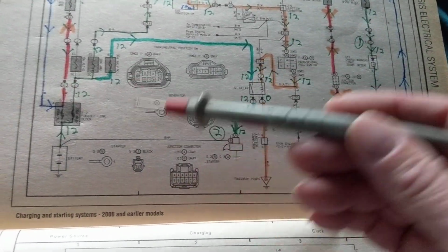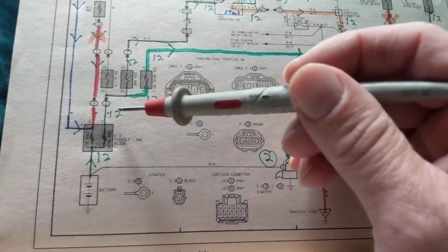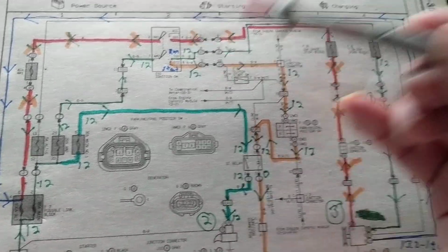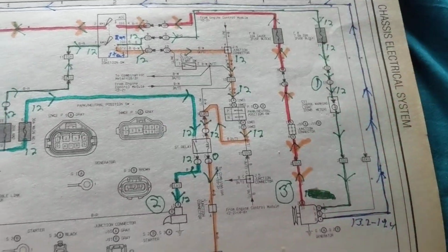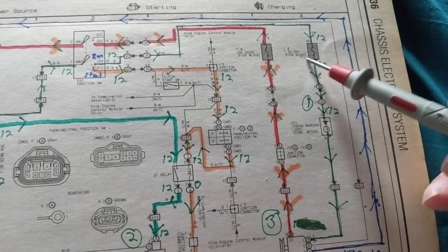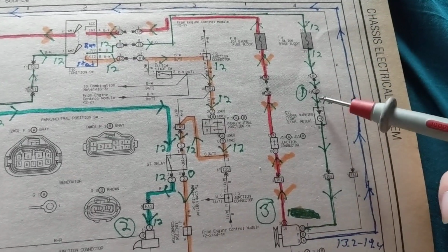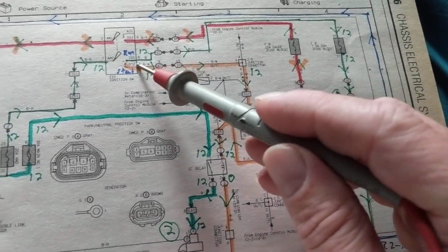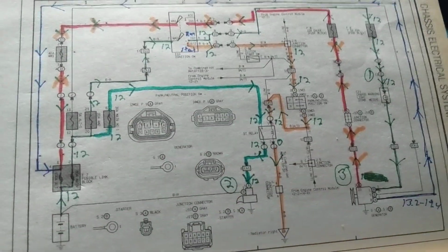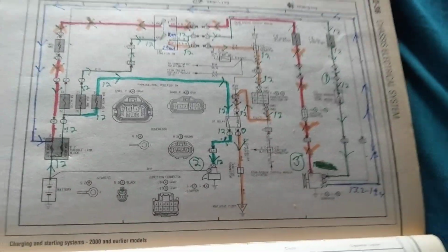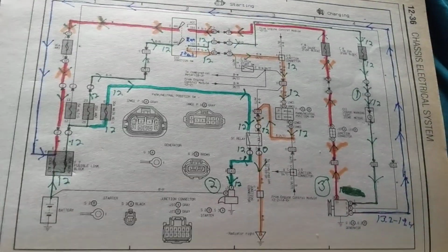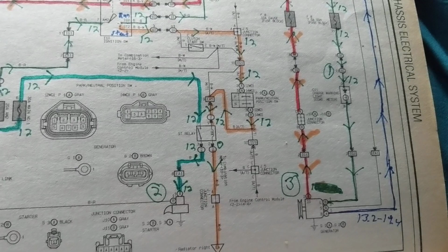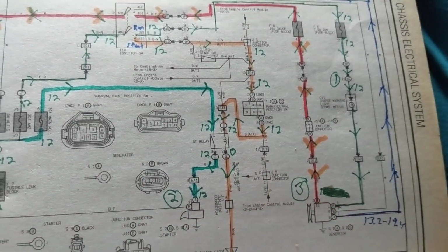This is a pro from a meter. Without even putting a meter at this point, or this point, or this point, you saw yourself when this lit, automatically the ignition switch must be good, the fuses must be good, without even putting a multimeter on it. This is how you troubleshoot. Use these bulbs, use these malfunction lights and all these things in your dashboard to tell you things.